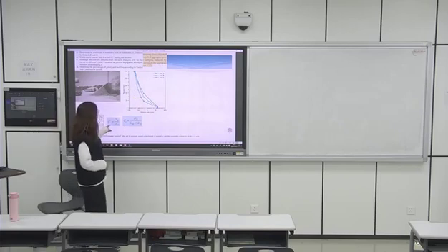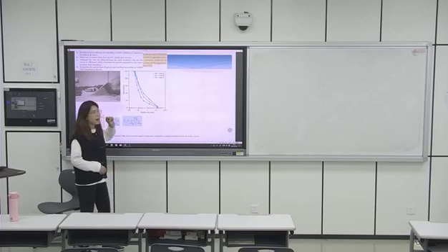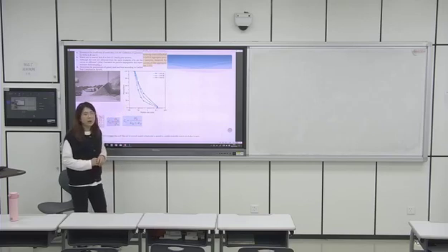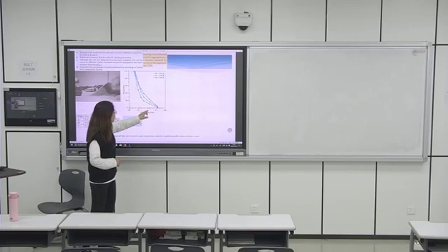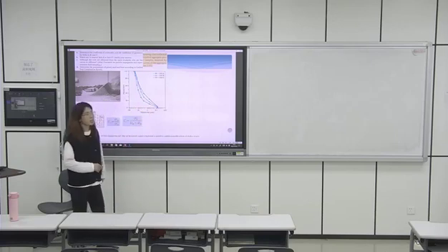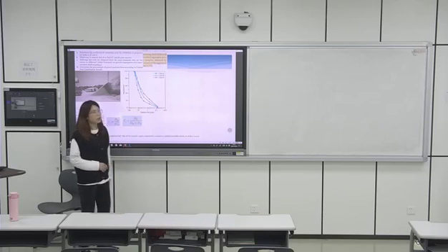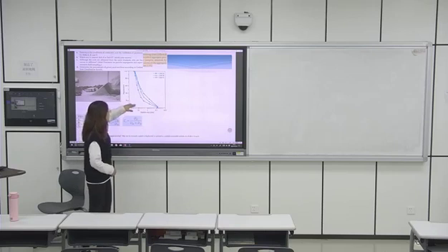Let's say one. For soil A, if you want to find D10, D10 is the particle size corresponding to 10%. 10 is in here, then draw a line, a vertical line in here. It is around 0.1, 0.2, 0.3, maybe 0.4 or 0.6. If you got the paper, it is much easier for you to get the answer, right? So it is the particle size corresponding to 10%.